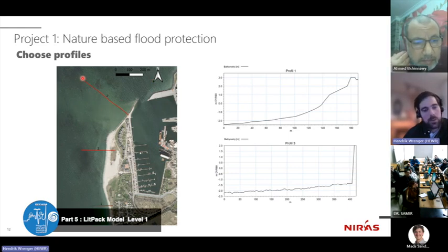So we have refraction, shoaling, and breaking, yes, but we don't have any diffraction along that line. So if parts of that profile are much more sheltered, for example for wave events coming from the south, maybe the last part of this profile would actually be affected by some diffraction around this little headland.